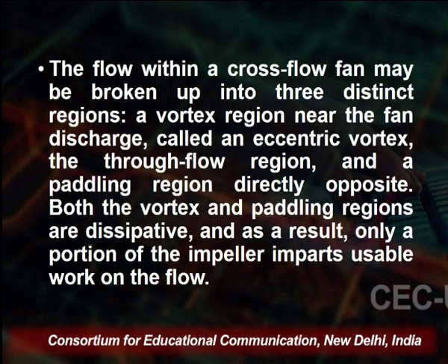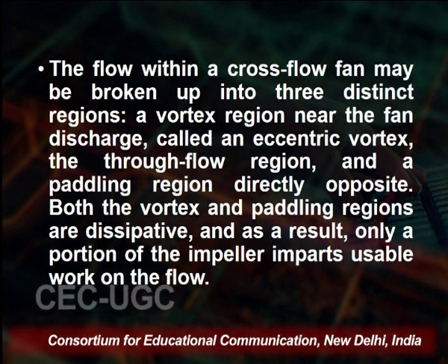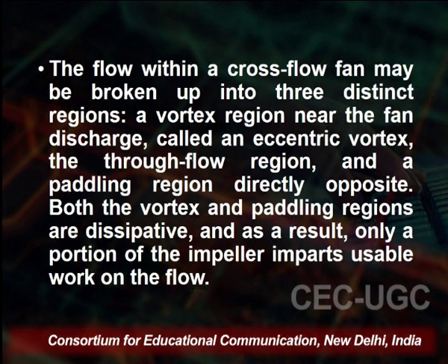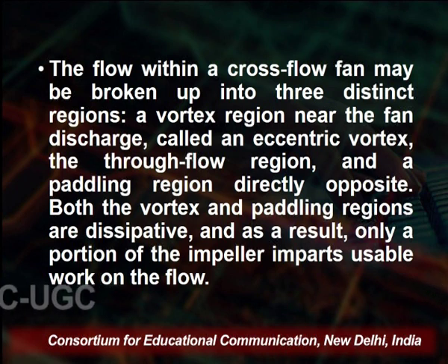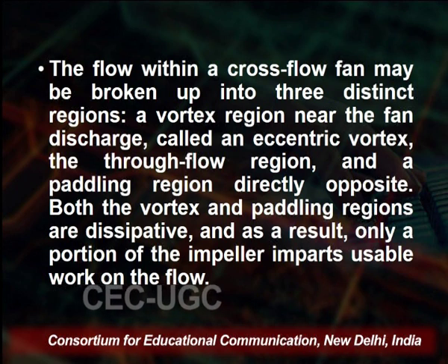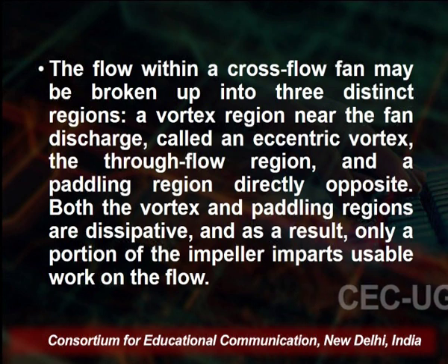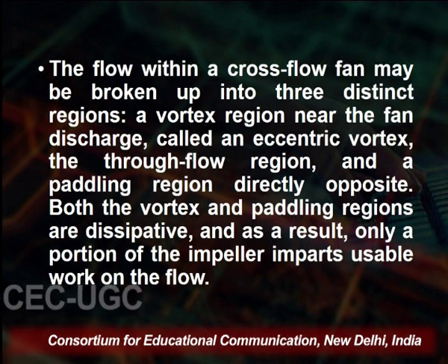The flow within the cross flow fan may be broken up into three distinct regions. Number one is the vortex region near the fan discharge, called the eccentric vortex, then the through flow region, and third is the paddling region, directly opposite to the vortex region.